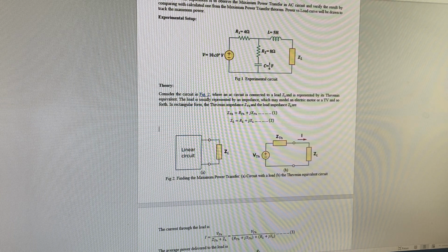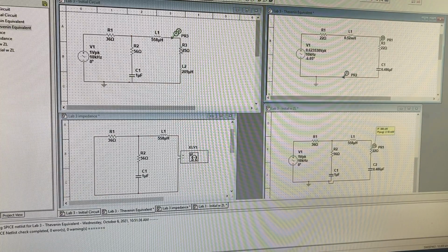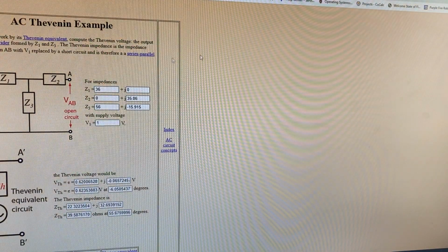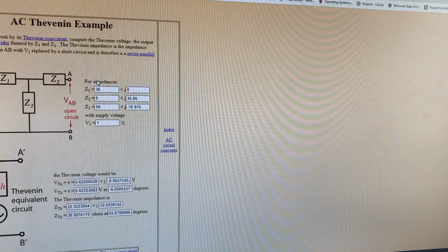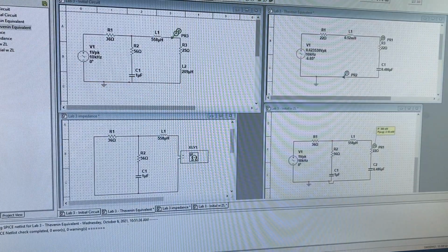And in fact, I'll turn to Multisim here. This is my starting circuit here. I can determine the impedance across these two nodes. I can use the impedance meter in Multisim, or I can use this little calculator that Hyperphysics provides. Just punch in my values. It tells me what resistor value to use and what reactance I'll need.